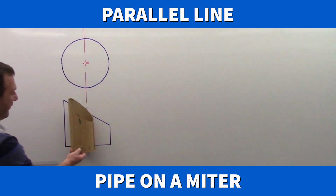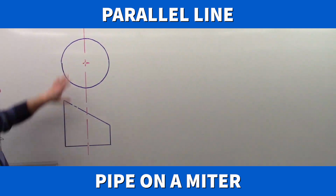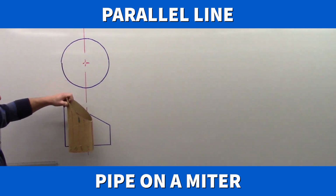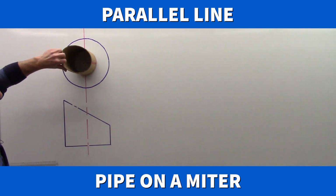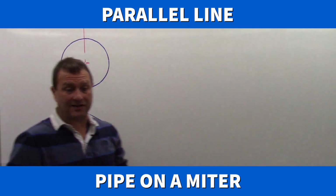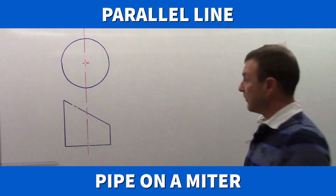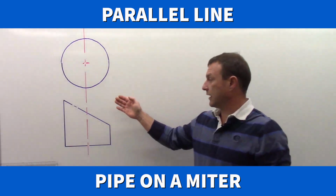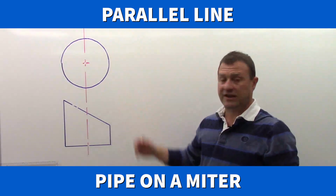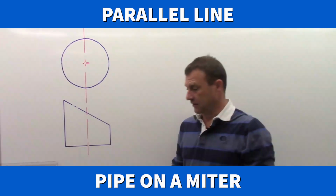So I have my elevation view, which always has height associated with it, and our plan view. So we're looking at it like this and like that, straight down on it. So that's one of the basic steps of parallel line, to get those two views established as complete as we can. And at this point they're not completed because we don't have any element lines in them yet.